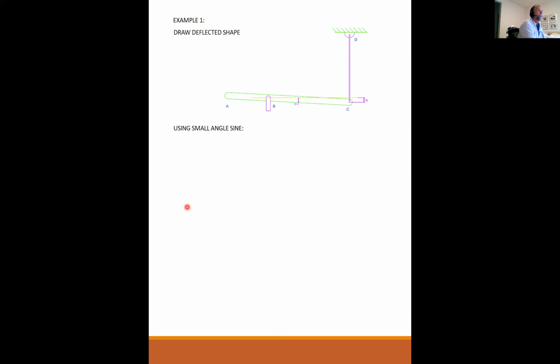Skipping for a moment the use of the law of cosines to get the exact solution, we're just going to use the small angle solution using our sines. We talked about this a lecture or two ago. dy is equal to sine of 3 degrees times x, which is 40 inches. So dy is 2.0934 inches. I am carrying a bit more accuracy on these numbers.